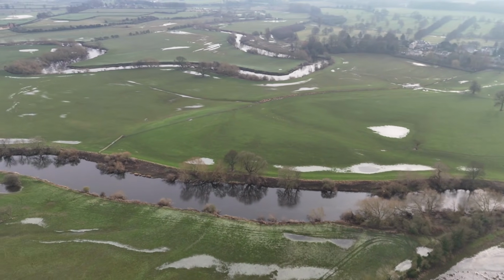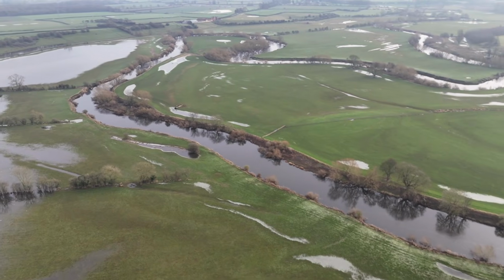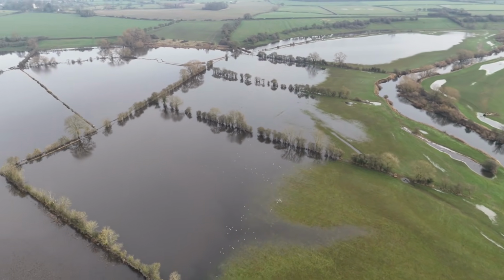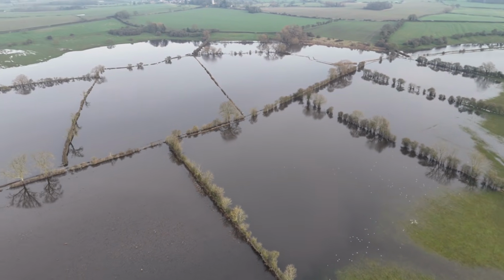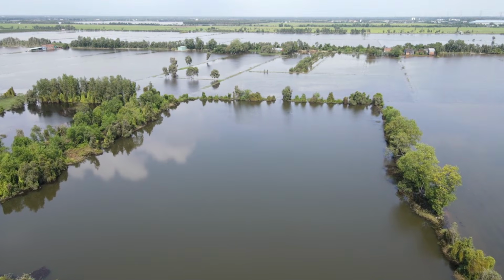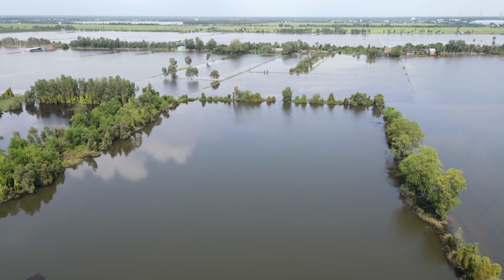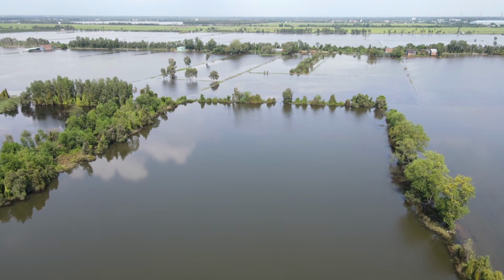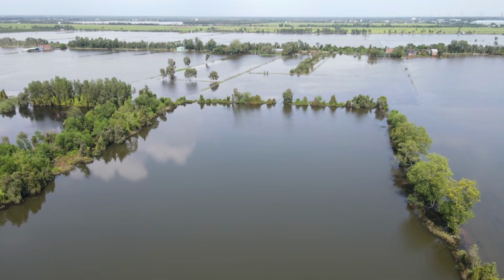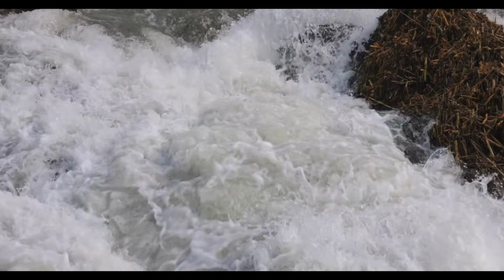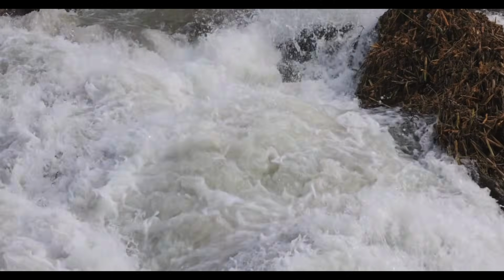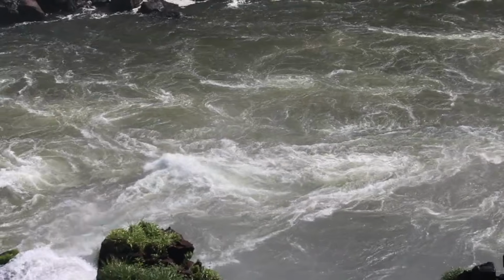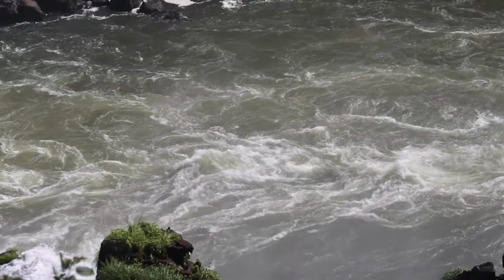One of the most counterintuitive aspects of the dam break wave is the difference between the dry bed and wet bed scenarios. If the wave moves into a dry valley, the leading edge is slowed significantly by friction with the ground. This creates a blunt, rounded nose of water and debris. However, if there is already a river or a previous flood layer in the valley, the wave can travel as a sharp, vertical wall known as a shock front.